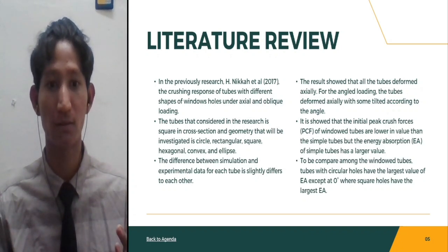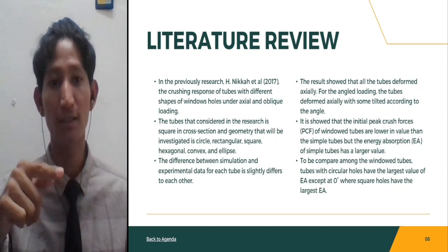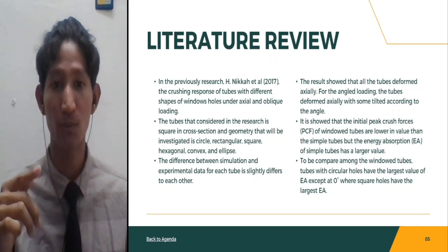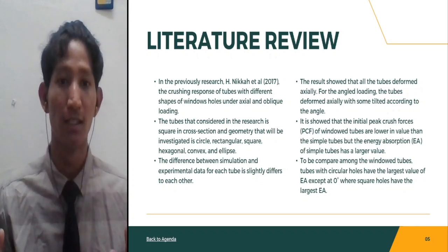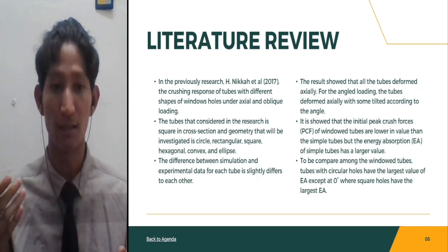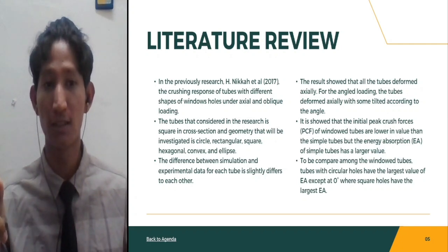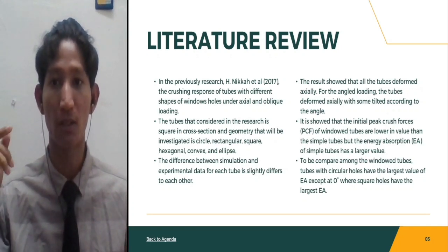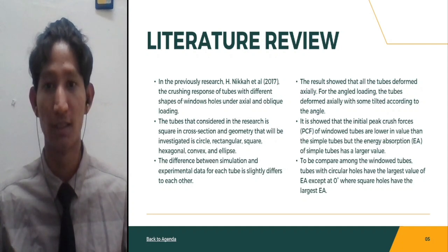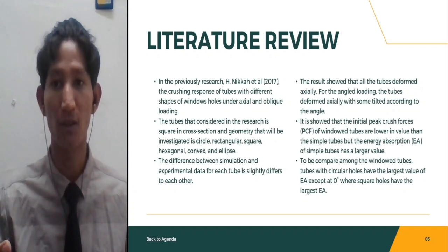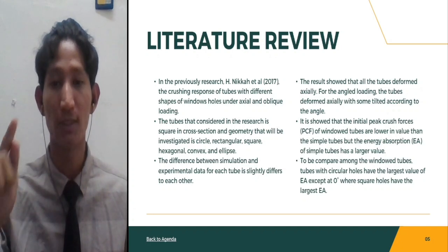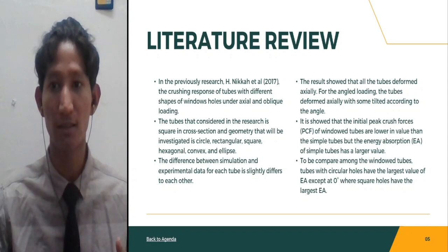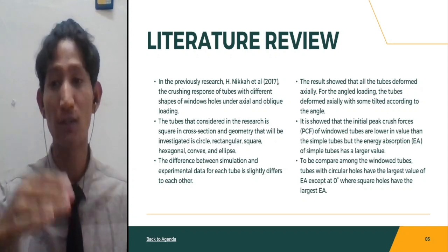The results show that the difference between simulation data and experimental data for each tube differs slightly, and the simulation data is acceptable when compared to the experimental data. The tubes are deformed axially. For the angle loading or oblique loading, the tubes deform axially, but there is some tilt deformation according to the direction of the angle.